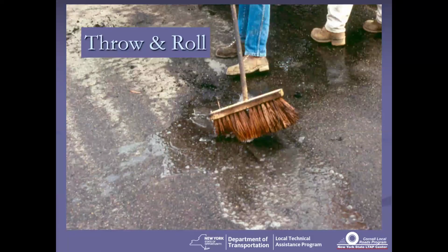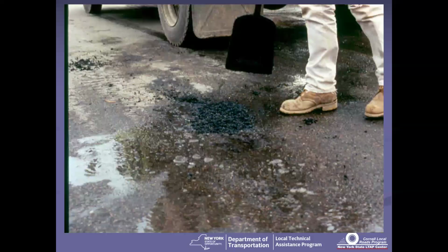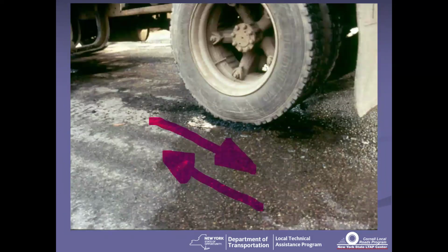The technique we strongly suggest is the throw and roll technique as opposed to throw and go. You try to get the water out of it, but not necessary. You throw that material in. I like this slide because if you look at that material closely, you're seeing the glossiness, and that's the use of the polymer in that material. It's an engineered material, and once you throw it in the hole, it's consolidating under its own weight. But to really make it work, you back that truck tire, that high pressure tire, back over it.